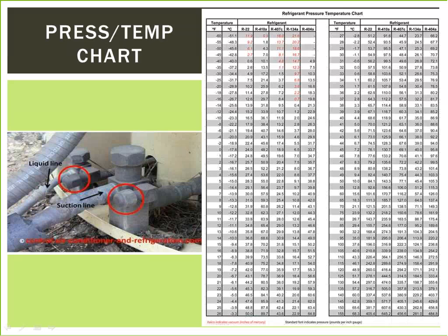So let's say it is 83 degrees outside. 83 plus 20 equals 103. Looking up 103 degrees on the pressure-temperature chart for R22, that corresponds to a 210 psi high side pressure. The same temperature on the R410A chart shows your high side pressure should be about 335 psi. R12 and R134A pressures will generally run around 30 psi on the low side and 200 on the high side. Once again, these will vary depending on ambient temperatures, but you can see that there is quite a variance from one refrigerant to another.